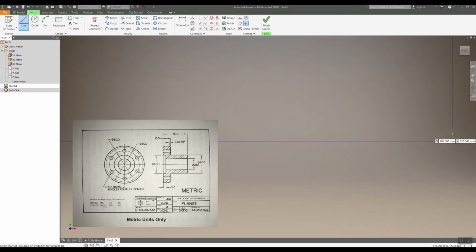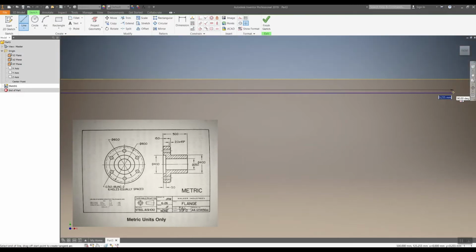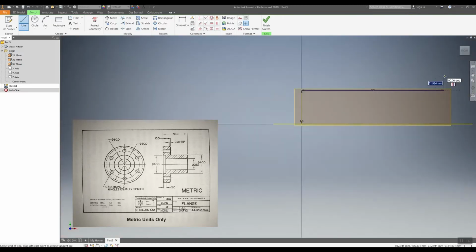You can snap to the edge of a dimension line, and that little spot can mess you all up, especially when we're talking this small. So be careful. We go up 75. We go in over here. You can see it is 500 long, but if we subtract 150 for the top part of this flange, we get 350, so it is 350 long.